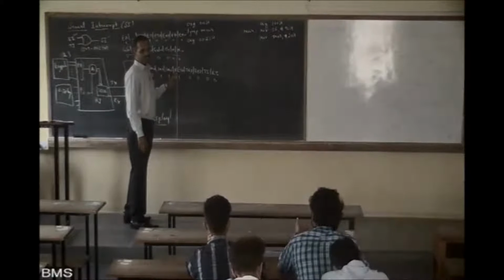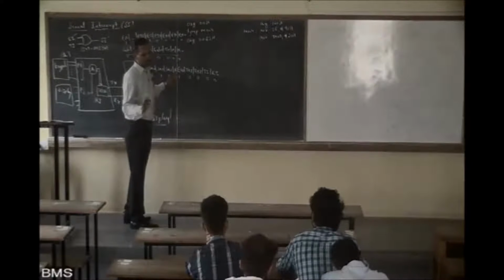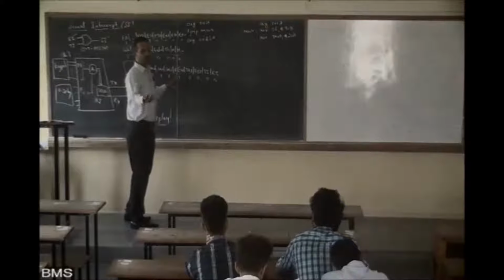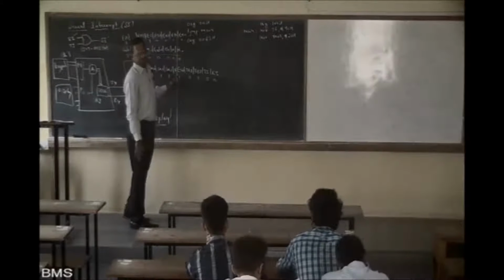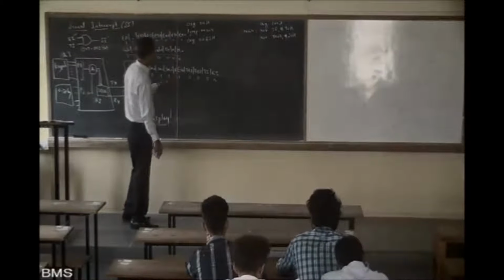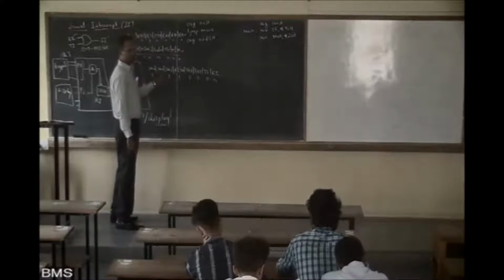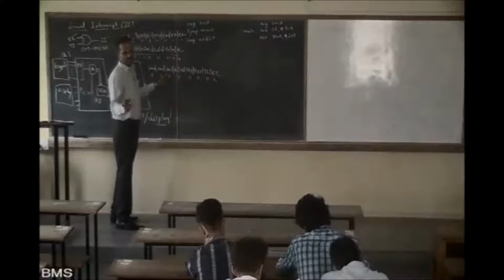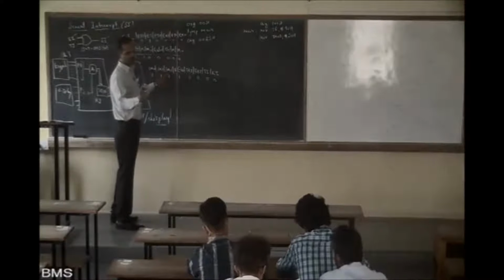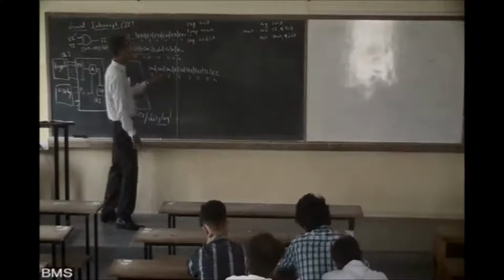REN is what? By transmission, it will be there always. If you want to receive data, you should enable it here. So this is receive enable. SM2, what is SM2? Don't worry about this bit. It is a multiprocessor mode, which is not there in your syllabus.